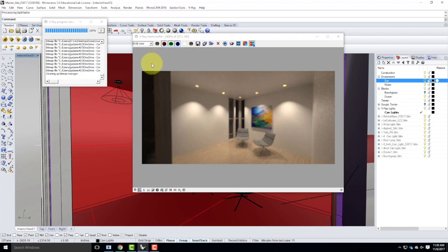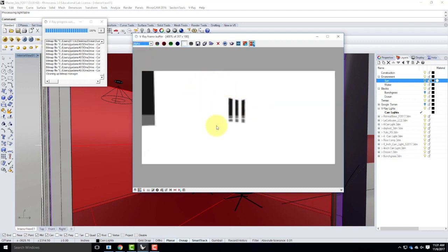I told you about those extra channels in rendering. They're accessible up here. You see RGB color is shown. If I click the drop down, these are all the different channels that I selected. For example, alpha will show us what's solid and what's background. So we can see this gray is really far away, this is up close to me, and then the black is the background. If I move down here, this gray is not because it's really far away, it's because it's semi-transparent. That's what alpha is: solid, semi-transparent, and fully transparent, which is up in the sky.